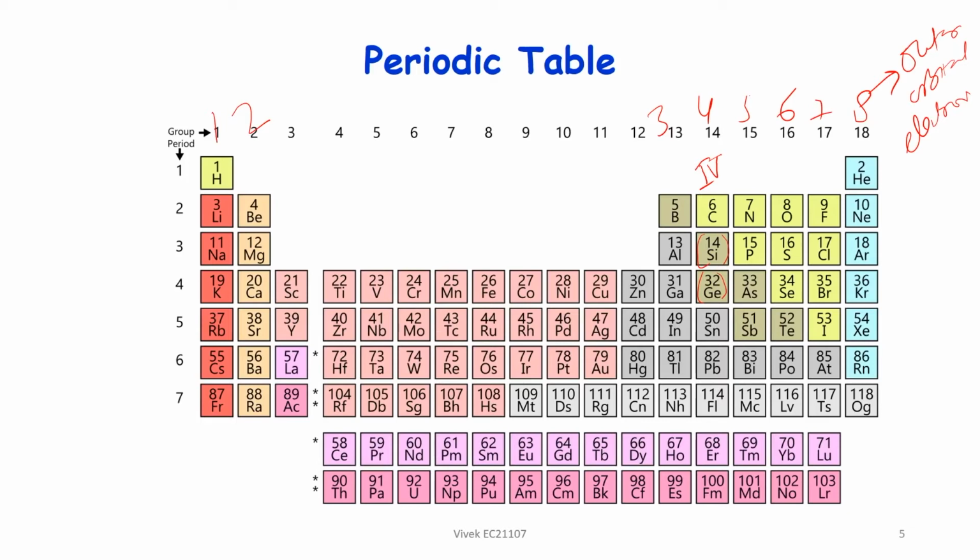Now there is another possibility to get a semiconductor with an average of 4 electrons in the valence band if you move one to the right and one to the left. To the left there is group 3, to the right there is group 5, and you can select an atom from group 3 and an atom from group 5.